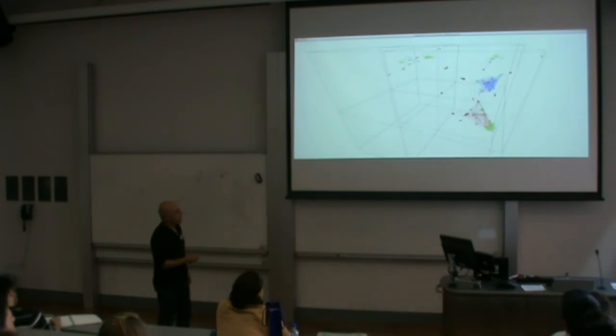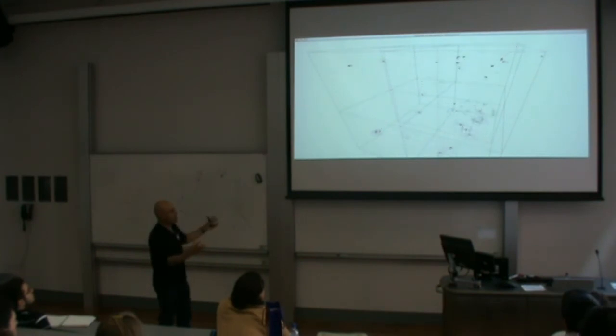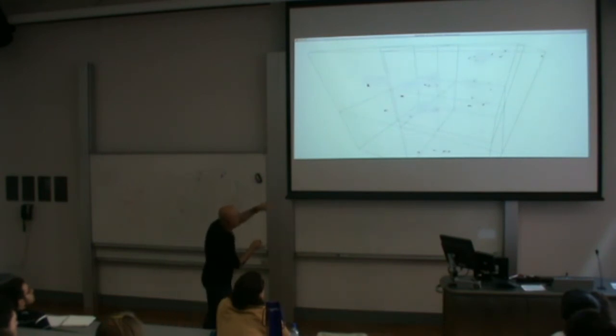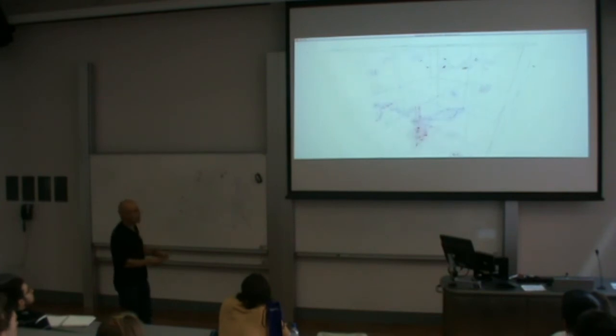You have several groups. Red robots can communicate with red robots, and so on. And when you can see a segment, it means that they are sufficiently close in order to communicate. When one robot goes to the surface, it is able to use a GPS and communicate to the others via the distances. They will be able to communicate some information about their localization. And all is solved in a distributed way. Here is represented the fact that it takes time for one robot to communicate with other robots, and this has to be accounted for, and it is modeled through delays. So it is a collective set estimation problem with delays.